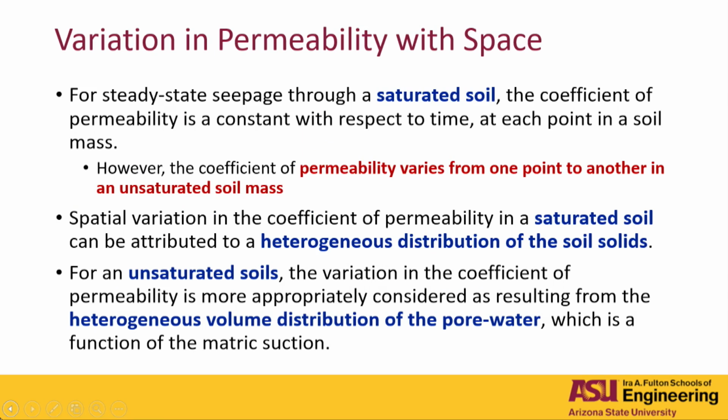This is important because I find that the main cause of inaccuracies when you model seepage analysis is the wrong value for these unsaturated hydraulic conductivities. We usually assume things, right? So this is something you really need to be careful about when you are running any one of these analyses. For a steady state seepage through saturated soils, the case that you all know, the permeability is a constant with respect to time at each point in the soil. This is what we assume.